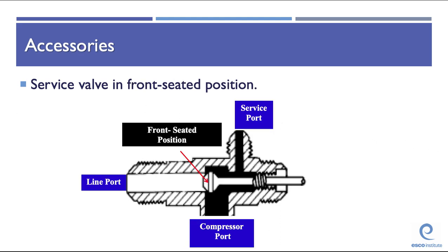A service valve can be in a front-seated position as well. When the service valve is in the front-seated position, the black solid color is where the refrigerant will flow. In the front-seated position, the line port is closed, and the compressor port is open to the service valve.